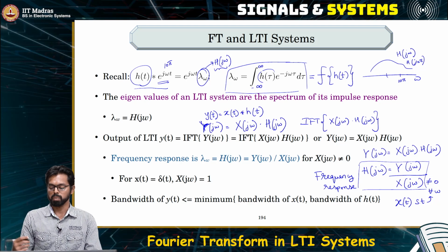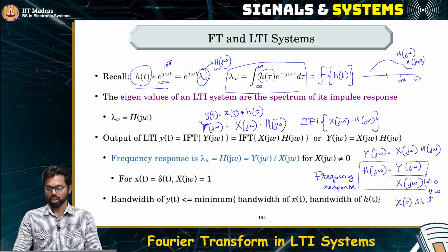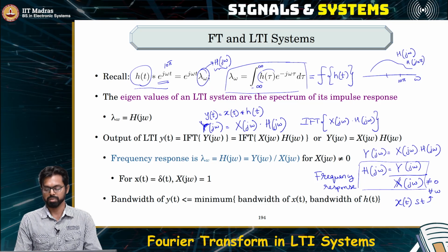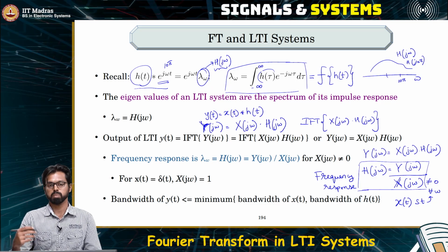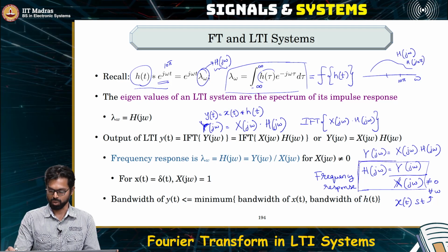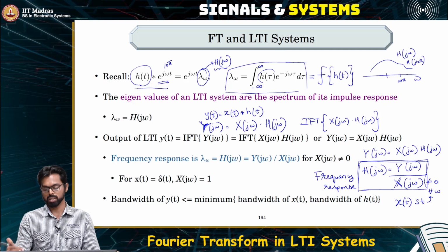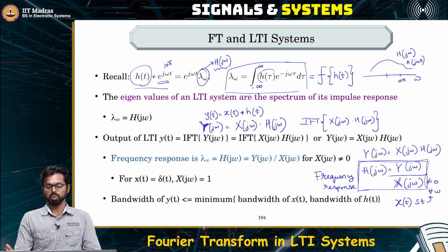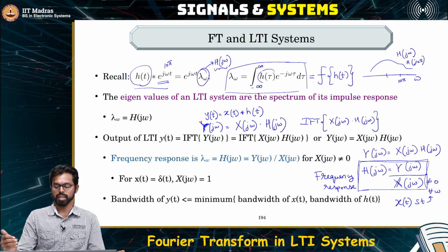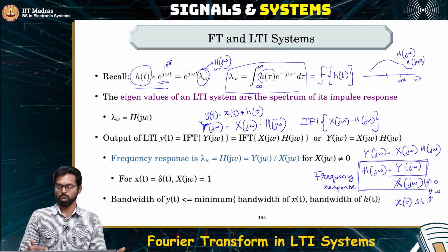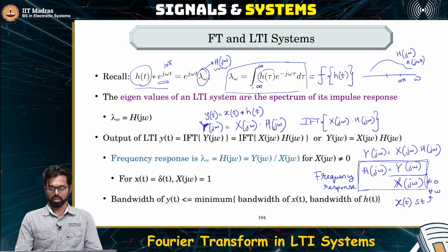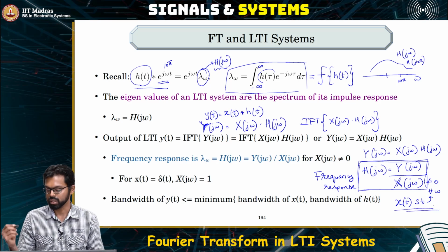So, we can feed in arbitrary signals where the spectrum of the input contains all possible frequencies. If you can feed in such a signal, and from the spectrum of the input and the output, you can compute this ratio which gives the frequency response. And the impulse response can be obtained by simply taking the inverse Fourier transform. So, now we have a very nice elegant technique with which we can find out the frequency response and the impulse response of a system without even feeding in an impulse, but any arbitrary signal will work. Only thing is the arbitrary signal should satisfy this property.